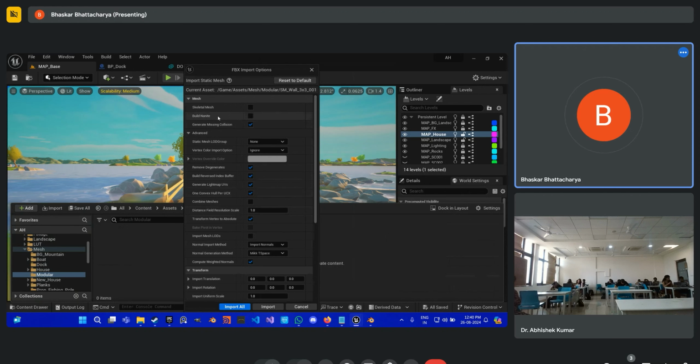If your asset is extremely high poly or extremely badly made, in that case nanite works. Otherwise, if your asset is already low poly, well optimized and well made, then nanite literally does not do too much for you. And also nanite is not supported on Android, it's only on PC platform. So it is something that you can decide to turn on, or you can just leave it.